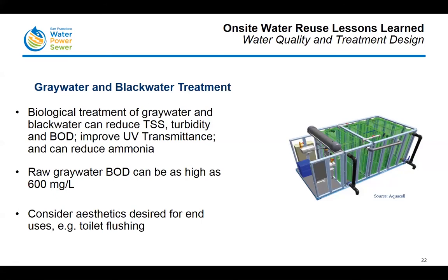So we've modified our program to require biological treatment to bring those high BOD levels in graywater down. And the last point is that aesthetics are an important consideration for graywater and blackwater treatment, in terms of how it looks, the clarity of the water, and the odor.